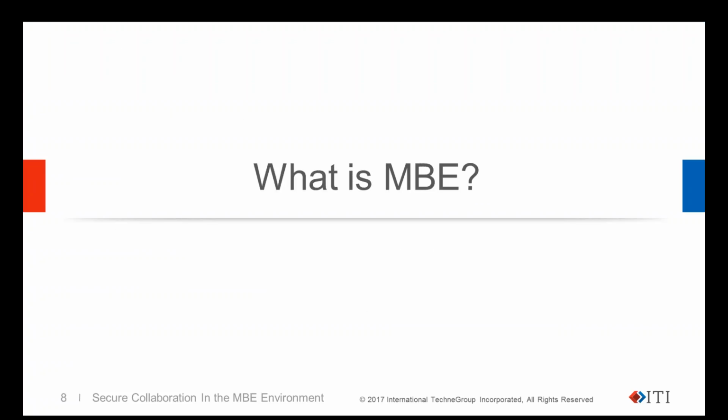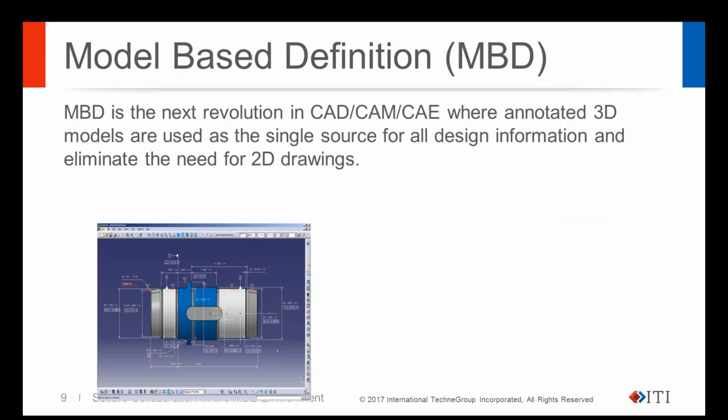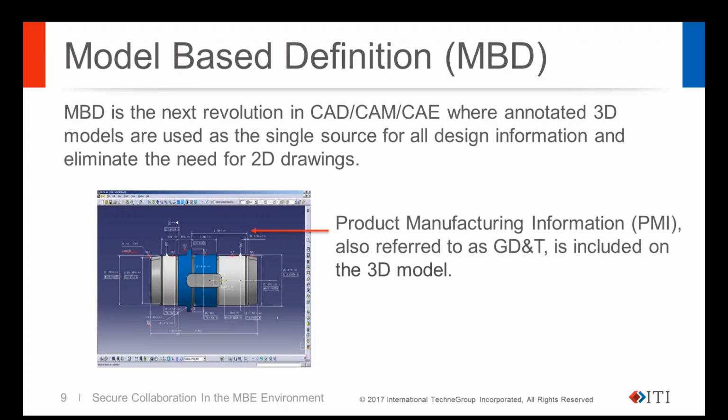So first, what is MBE? There's a lot of acronyms that fly around, MBX something. MBD is usually equated to model-based definition, and the notion is that instead of having a two-dimensional drawing, you now put more information into the 3D model, including the annotation, product manufacturing information, or GD&T, depending on the CAD system you may be using. So you don't have a drawing anymore, everything's in a 3D model.